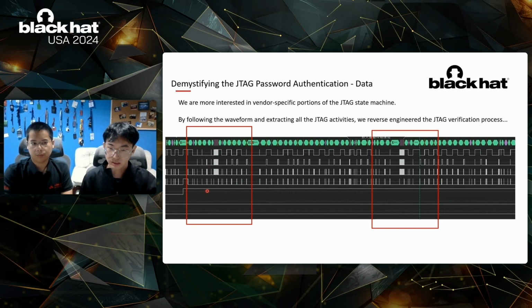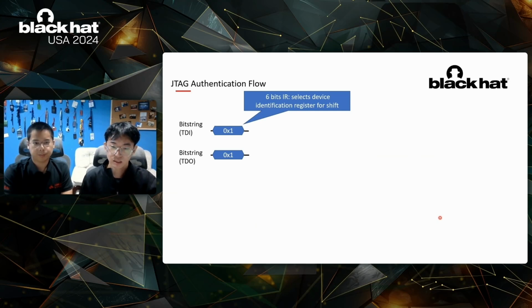In this process, the areas enclosed in the red box are nearly the same. We will conduct a more detailed analysis of this similar process. Now we only know the meaning of some of the 6-bit JTAG instructions taken from official files, but we don't know the meaning of the 10-bit JTAG instructions. However, let's give it a try and analyze.